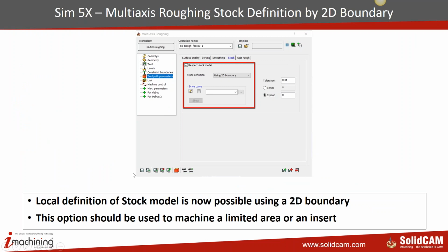Stock definition in multi-axis roughing can also be done using a 2D boundary. So if you don't have a surface, then you could just define a 2D boundary. But if your part is twisted like that, then it becomes very difficult for the 2D boundary to handle it. In such cases, you can revert to the local stock definition using surfaces.